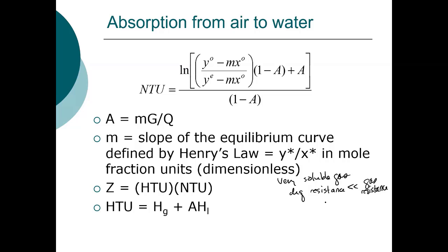And there, this Hg or Ky A, the mass transfer coefficient across the gas film, will predominate, and that dominates the transfer. If you have insoluble gases, then the opposite is true. There, the liquid resistance is much greater than the gas resistance, and H sub L or Kx A dominates.